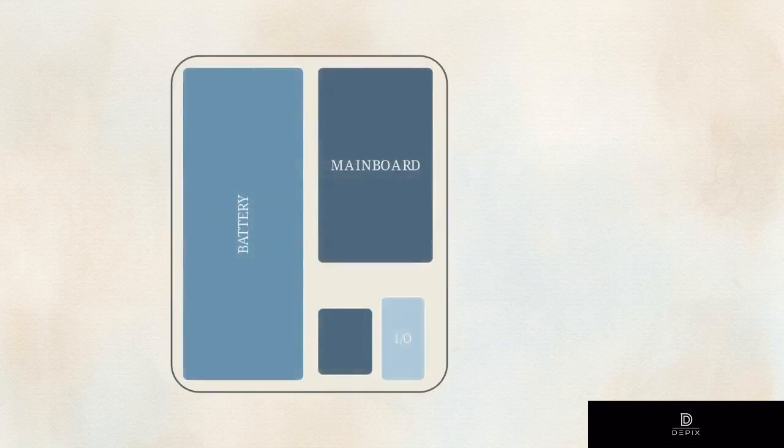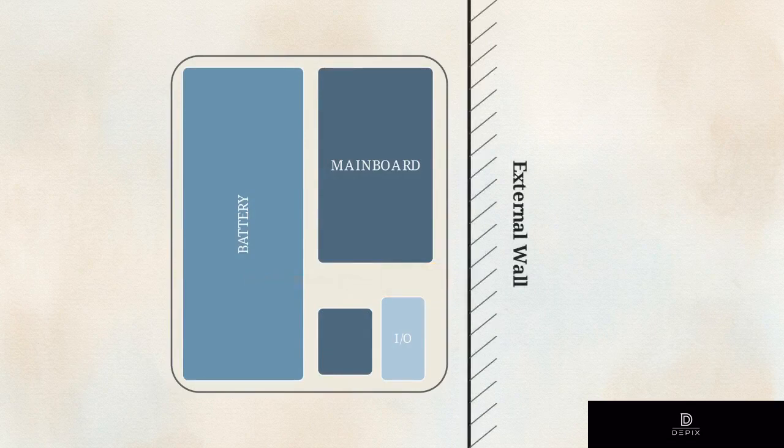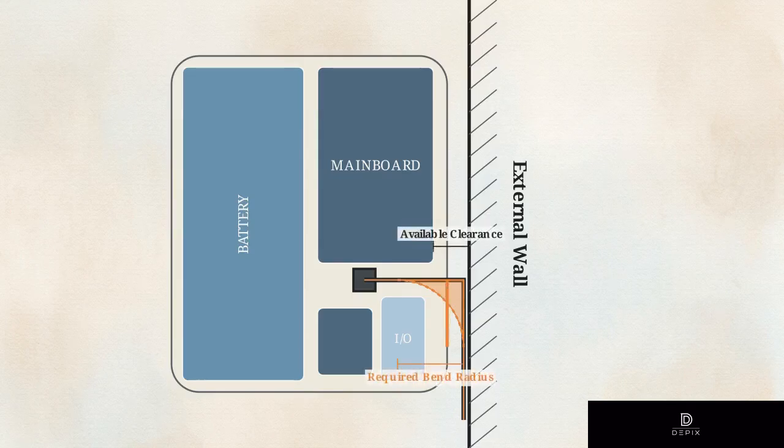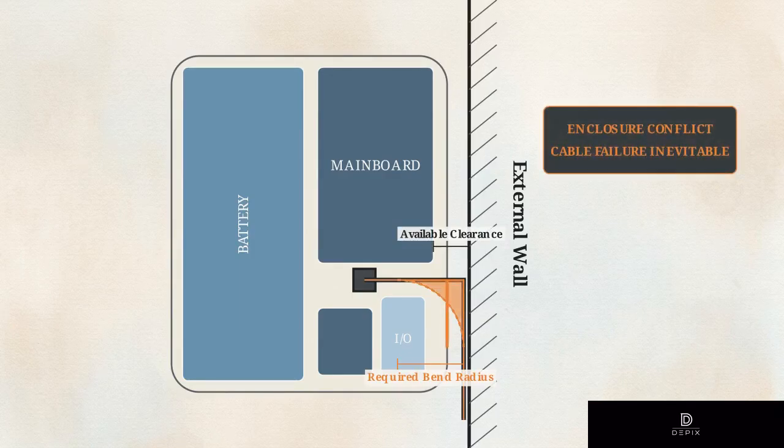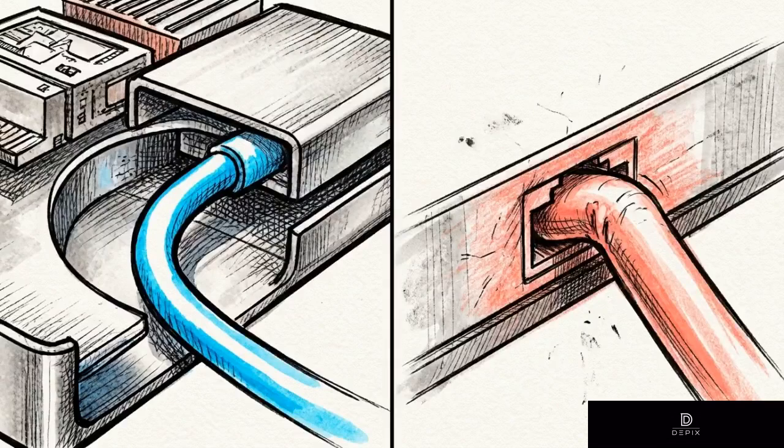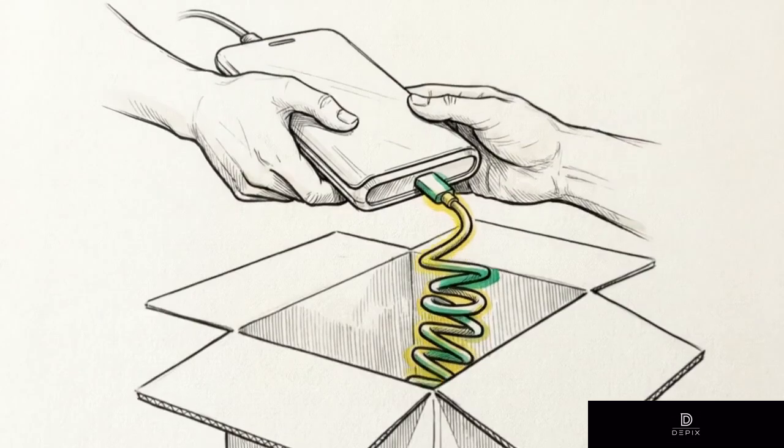First, the exit point for the cable becomes whatever random space the internal components left available. Next, the exit angle is dictated by whatever the external wall allows. A lead leaving the back of a device that sits against a wall is forced through 90 degrees before it has traveled a centimeter. Finally, the transition length is starved. Proper strain relief needs physical room to build an arc, and a shallow housing simply has no space remaining for that geometry.